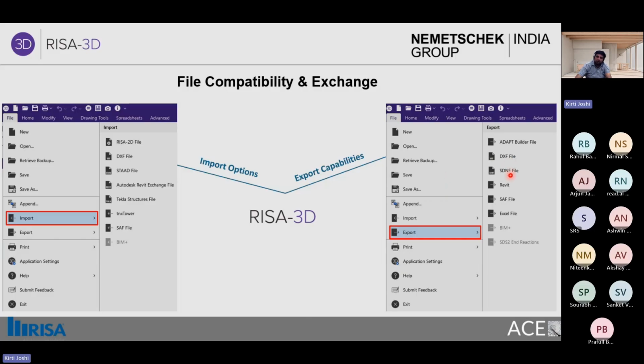The file type STNF is the Steel Detailing Neutral File. That is a file format used by a number of CAD and steel detailing programs. This format is superior to the DXF export, and it contains the member size and the orientation information as well. You also have the ability to import and export file types in the ESAF format, which is the Structural Analysis Format file.